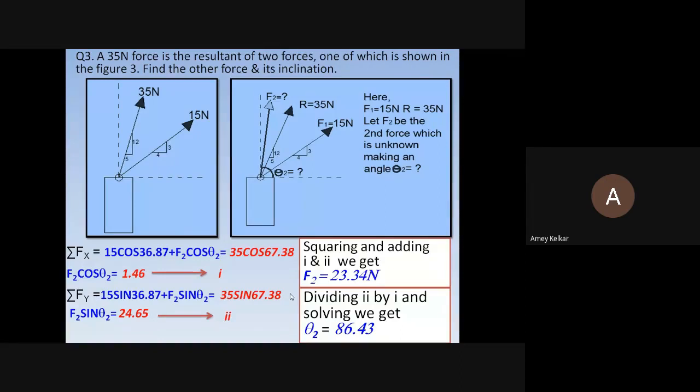Basically, where you all lacked is understanding the statement of the example itself. I cannot teach you all sum by sum because sums are many. This you have to develop. Firstly, you have to understand it is all about only summation Fx and summation Fy. Some forces are given, we want to find the resultant. Sometimes the resultant is given, we want to identify the force. As simple as that.